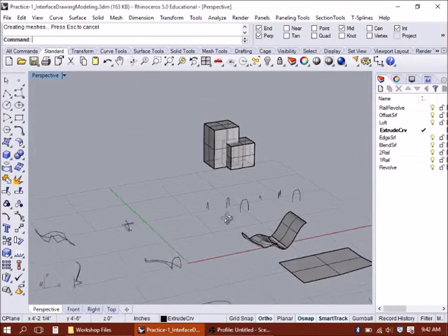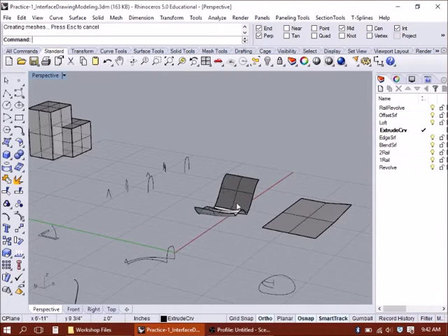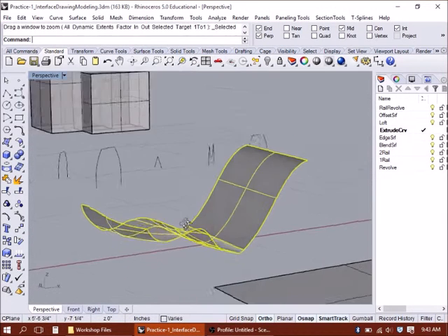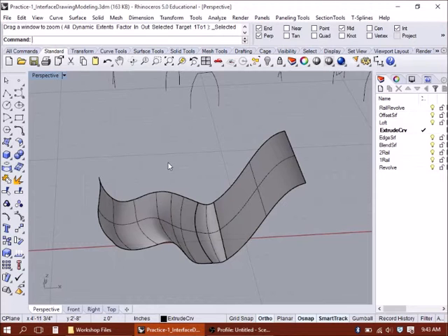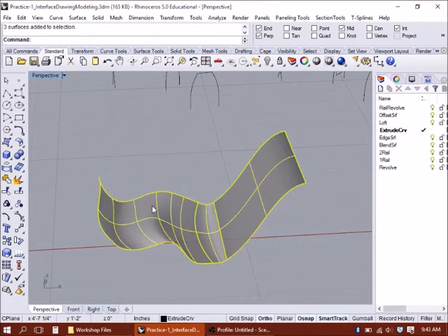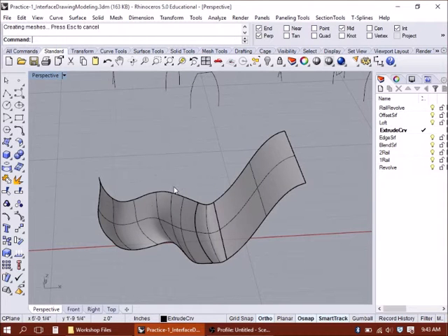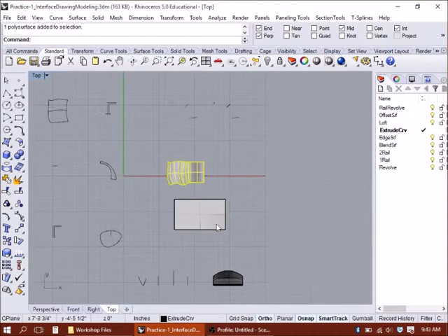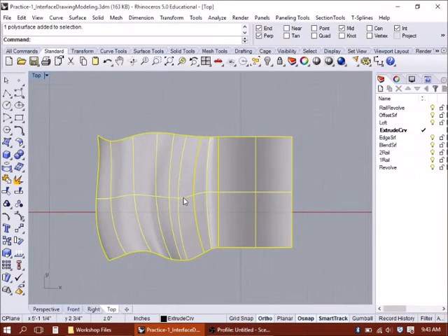The other thing I think people that have been working with, or could have been working with a little bit more, and I showed a bit of this some time ago, but I'll just review different ways that we can scale objects in Rhino. I'm just going to join that quick. Let's see, I'm going to go into the top view. And so say this overall form is fine, but maybe I wanted it to be a little bit more narrow.